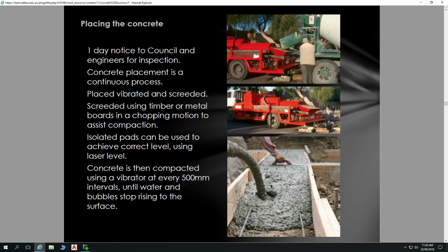And so that concrete vibration has to happen. That's done by this shaft with a two-stroke motor that drives this little vibratory shaft, which is just jammed down into the concrete. It's important that shaft doesn't go whacking against your reinforcing. If it hits your reinforcing, it shakes around like this, pushes all the coarse aggregate away from that reinforcing. You get weaker concrete around your reinforcing.